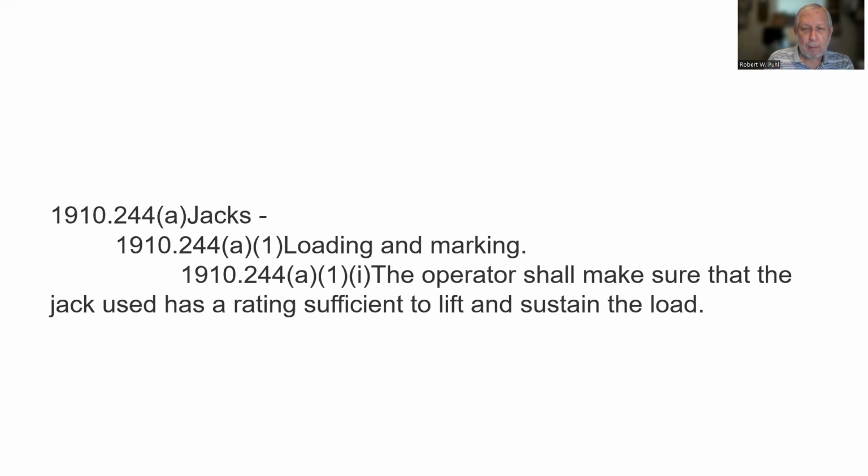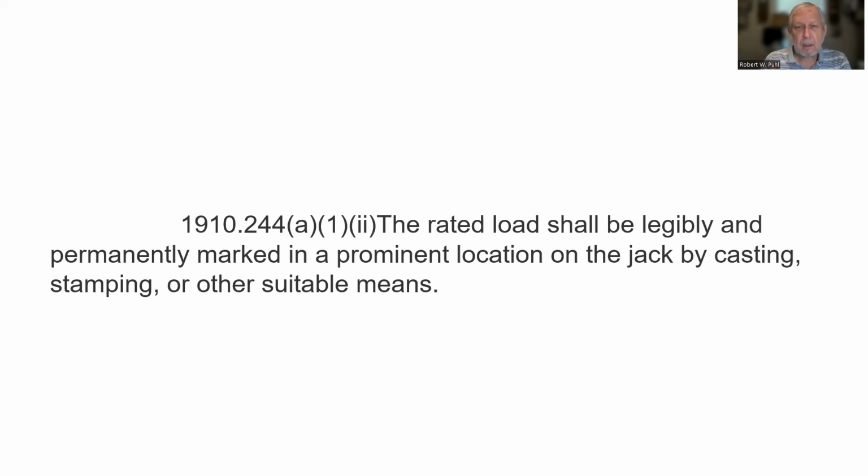Jacks, here we go again, loading and marking. The operator shall make sure that the jack used has a rating sufficient to lift and sustain the load. Makes sense. The rated load shall be legibly and permanently marked in a prominent location on the jack by casting, stamping, or other suitable means.